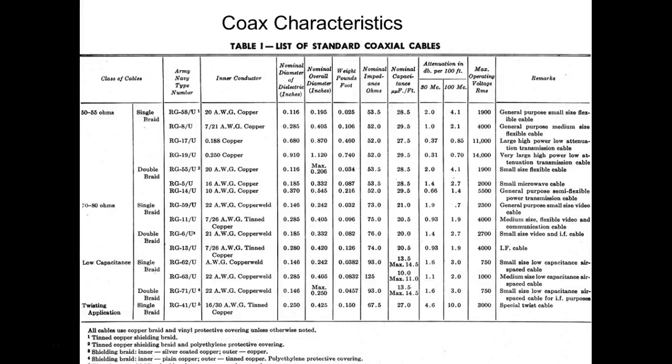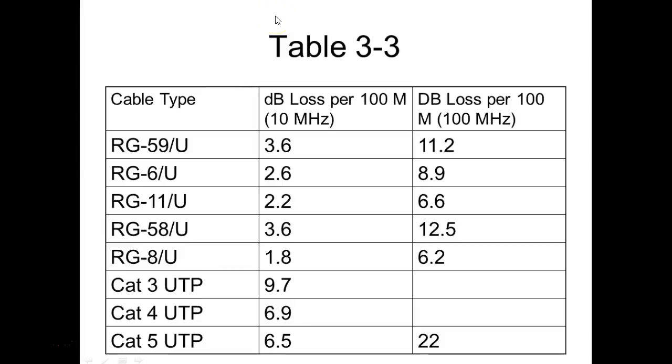Does that make sense? So if you look at the cable that drops down, that they actually run all the cables with, it's going to be a bigger gauge cable, but it's still going to be a 50 ohm cable, impedance, right? You understand that? So get the difference between impedance and resistance. They're two different things. Impedance comes into play on AC, right? You understand? And resistance is strictly what? It could be AC or DC. Now, I know y'all can't see that. I'm sorry.